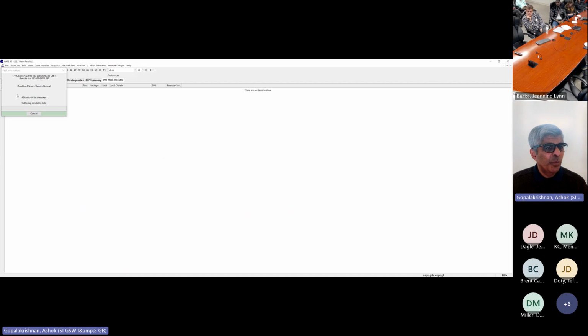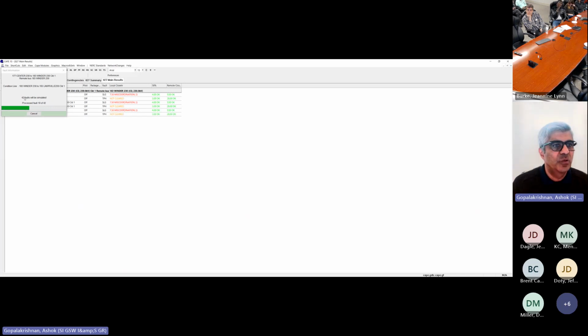So you can see in the pop-up on the left, it says 42 different conditions will be simulated. But we had 2 fault types and 3 different fault locations, right? And then we added on the contingencies to it. So you basically have 6 different scenarios multiplied by the number of contingencies to be studied, and that gives you the 42 faults to be done.